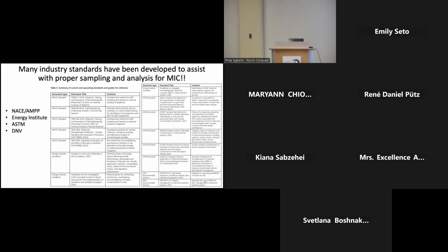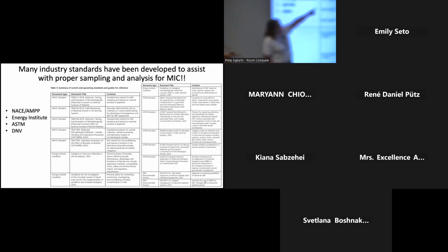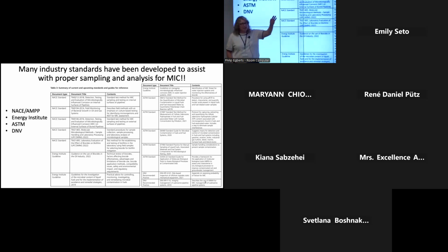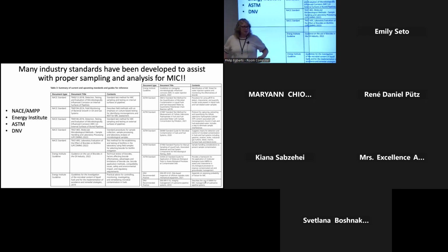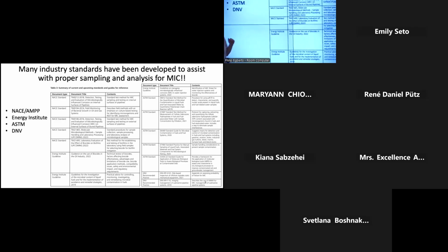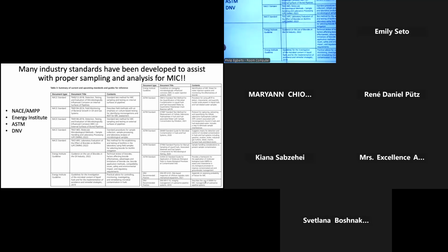This NACE standard TM0194 was last updated in 2014. Just last week, a new revised version was accepted by the voting members as a new standard, and it's really field monitoring of bacteria. The scope was expanded from oil and gas to broader industrial systems.